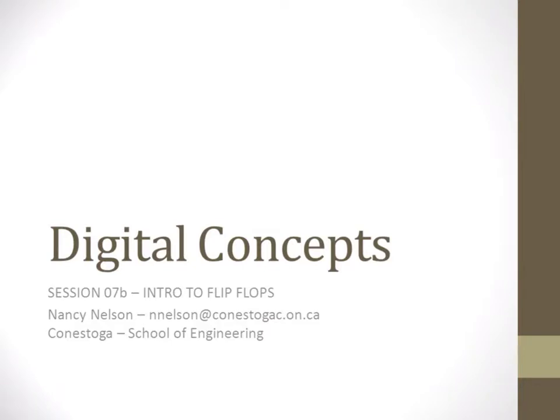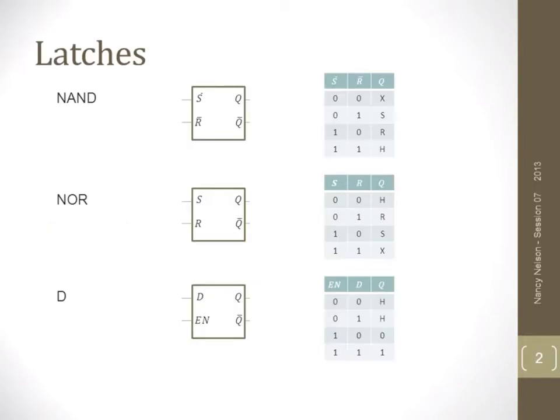In this session, we're going to take a look at the difference between latches and flip-flops. Last time we looked at three latches, the NAND latch, the NOR latch, and the D latch. The NAND latch and the NOR latch are our two basic latches, and both of them are called set-reset latches. They both operate a little bit differently, but perform the same basic function.